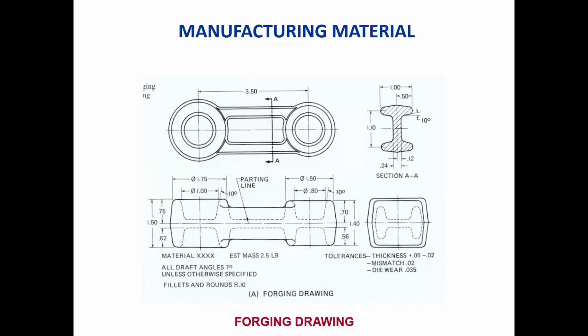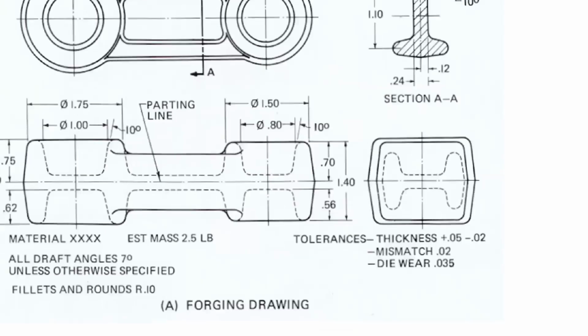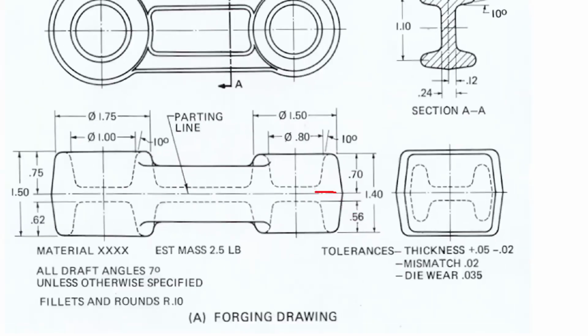There's still a parting line. So in this case, not all castings or forgings have a 2-part cavity. It could just be a 1-part, but there's still a parting line where it hits the flat base. So you can always see that seam. And the draft angles happen from that seam outward. So what I'm saying is, here's the parting line. Going this way, it drafts this way, right? And going up, it drafts the opposite way.